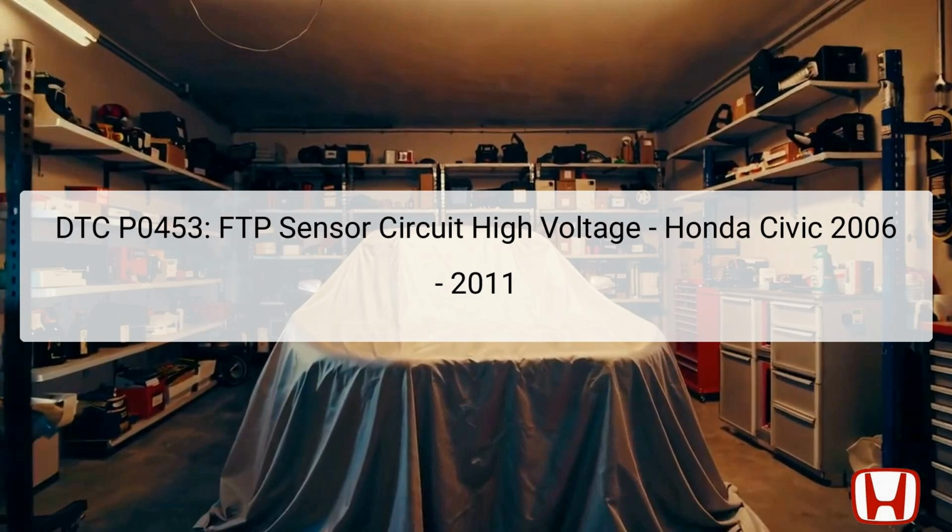The FTP sensor is critical for monitoring fuel tank pressure and aiding in the detection of evaporative emissions leaks, thus ensuring vehicle environmental compliance. The diagnostics for this error require careful observation of signals while using the Honda Diagnostic System (HDS) tool. During the process, it is vital to document freeze-frame data and onboard snapshots, as they provide insights into specific vehicle conditions prior to the error occurring. This guide will walk through detailed steps to diagnose and resolve the issue effectively and ensure your Honda Civic runs efficiently.